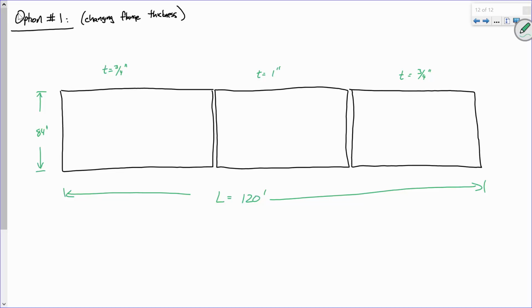Okay. Now here's what they're going to do on the fabrication process. First thing they're going to do is do a beveling operation right here. And the beveling operation is, if I have a thinner plate being welded to a thicker plate, the idea is to bevel some of this off so that when it's all said and done, it looks like this, so that I can start filling it with weld and welding those together. Something about like that, right? So we're going to bevel these ends, right?